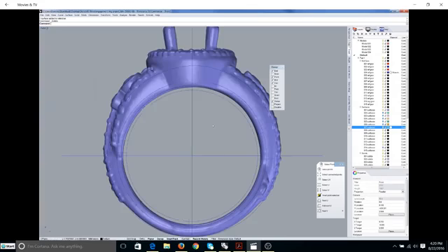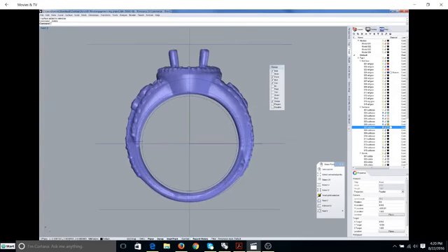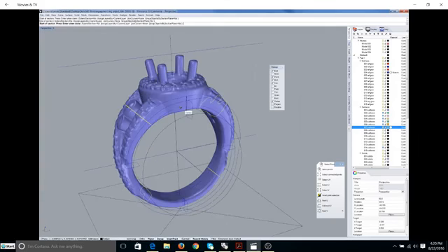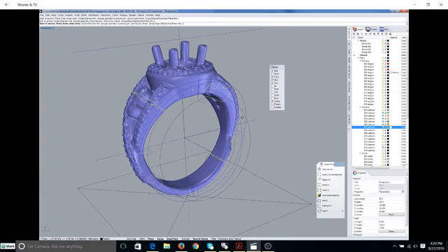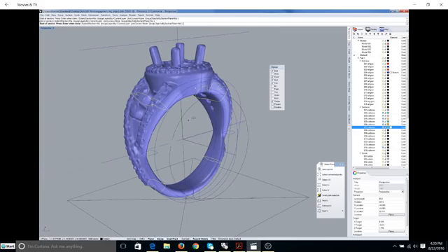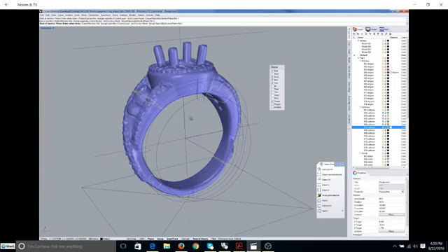Again, we can use a section tool on this if necessary. The only downside about the section tool is that it's going to go across the whole model. So as I put one across here, again, it's going to go to the opposite side. One way you can also work with this is to just put mesh planes in there where you need them and capture information that way with a mesh intersection. So there is a number of ways of capturing the information here, but it's all very, very usable, and it's very, very fast.